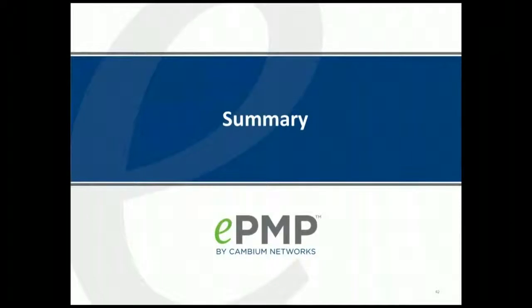It's probably the most efficient point-to-multipoint solution on the market today. For example, it supports 256 QAM modulation, which means that in a 20 megahertz channel, you can get 125 megabits per second, whereas the ePMP supports 64 QAM, so it's 100. So if you need that extra bit of bandwidth in the 20 megahertz channel, then the 450 is the solution.